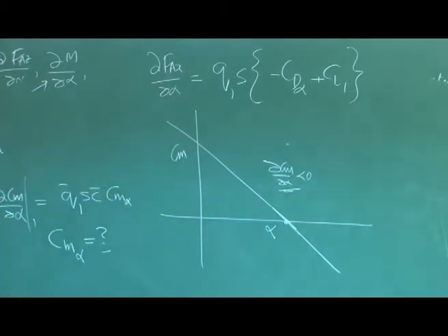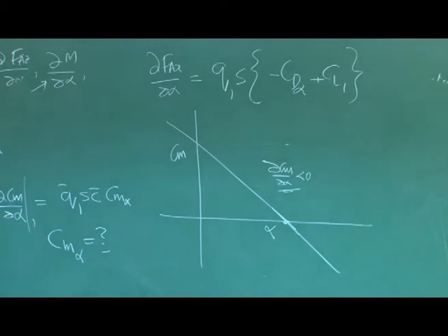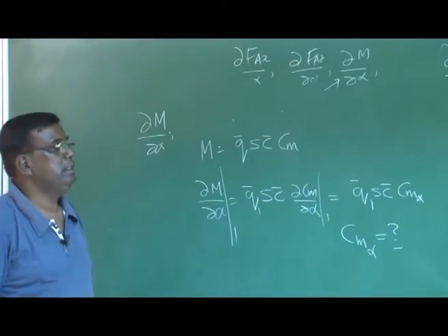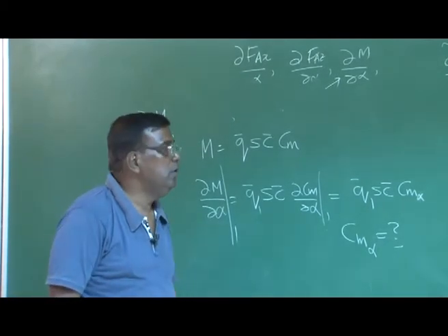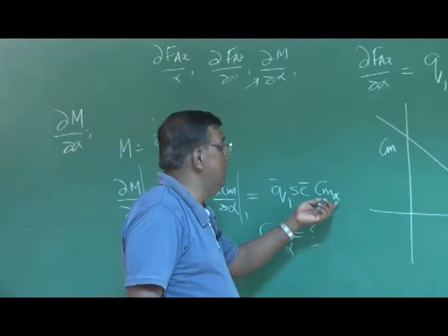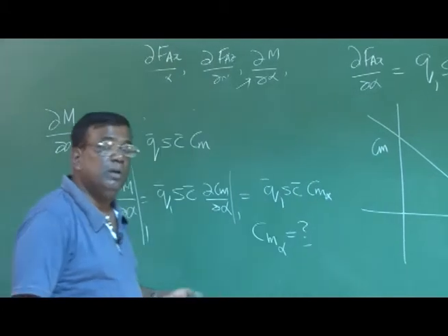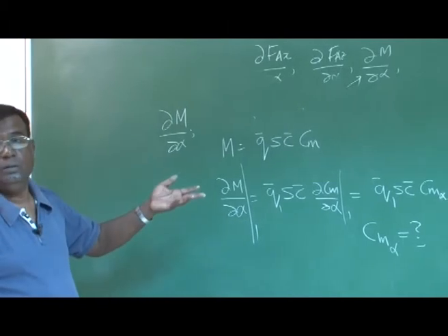So this is the condition for static stability, right? Typically this value will be negative, and you also cannot go on making this more and more negative, because more stable means difficult to control. So there is a typical range of values the designer will select for an airplane to have adequate, comfortable static stability, which are known.